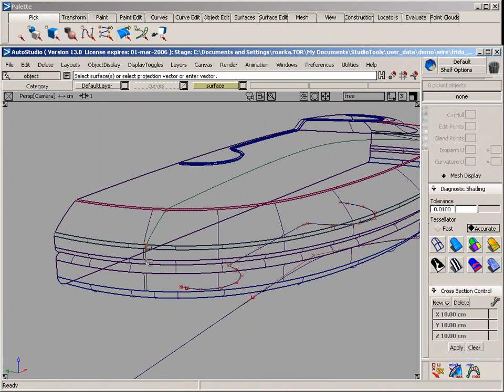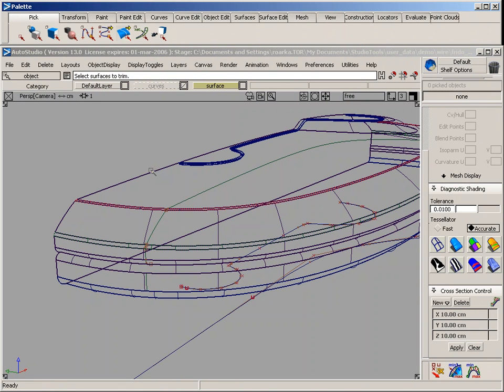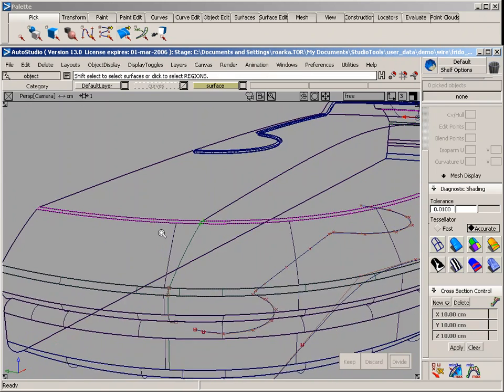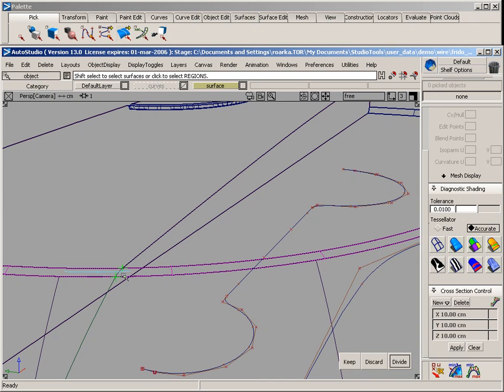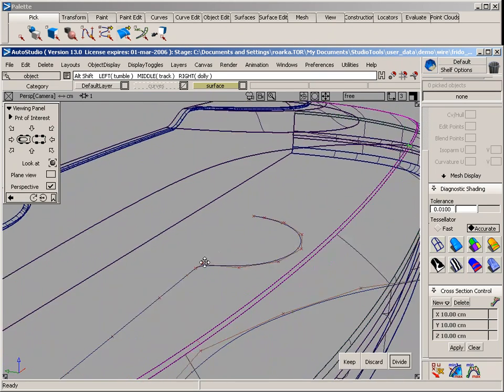and I will now start to trim divide some of these things. So for that, go to trim surface. I'm going to start with the top one. Divide these two areas. Now for the next one here, the small surface fillet that I created, I want to make sure that I zoom into this area so I can choose this and this side. And there's something else that you need to keep in mind when you're doing this with the surface fillet, which is all the way over here on the other side.